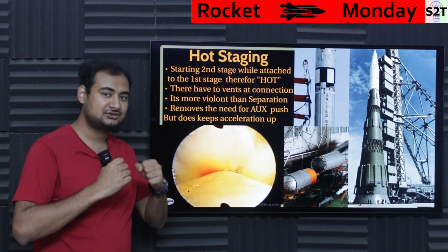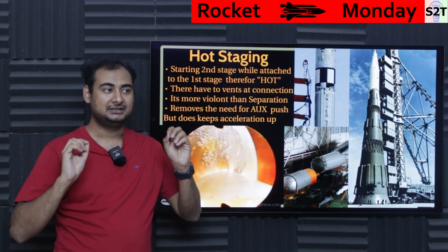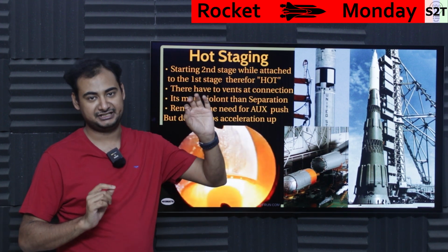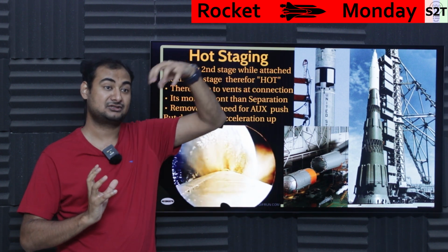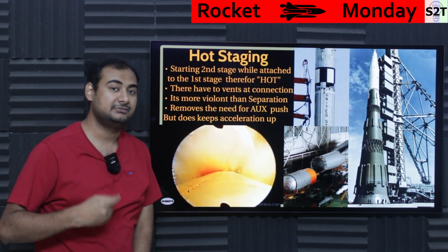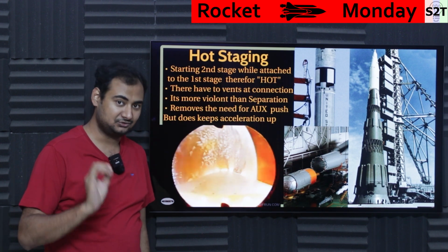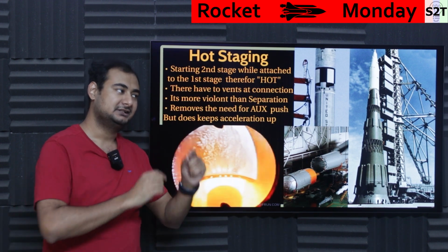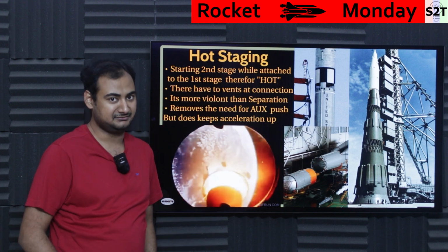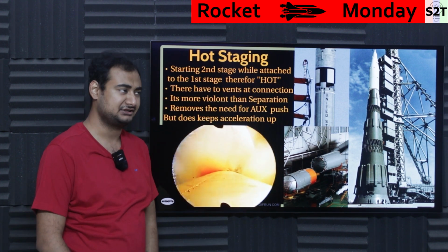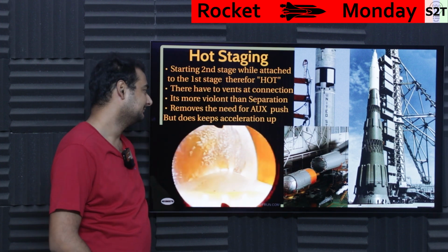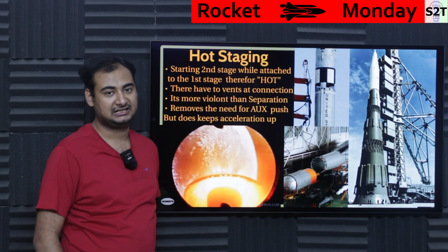And another benefit, because you are never shutting off, your momentum is constantly maintained. There is no point where it's not going like that. The velocity is constant, very smooth. So you do get a bit of payload boost, a little bit, but you do get it. And if you're talking about a big ass rocket, that little bit does pile up to a very big number. So that's what we call hot staging. Many countries do that. For example, India's GSLV Mark II, and the United States, Russia, all of that.